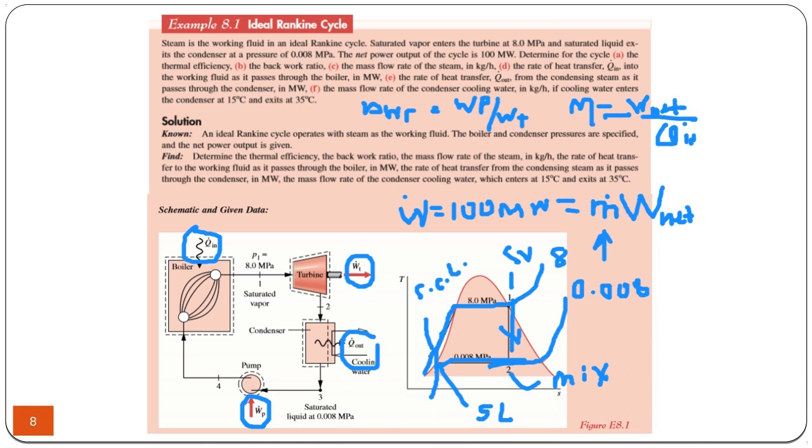And because it's a heat exchanger, you remember from previous weeks, in a heat exchanger, Q heat should be equal to Q cooled, because heat transfer from one side will be taken from the other side. So if you know the Q condenser here, it should also be the heat taken by the cooling water, which will be calculated from just m c delta T.